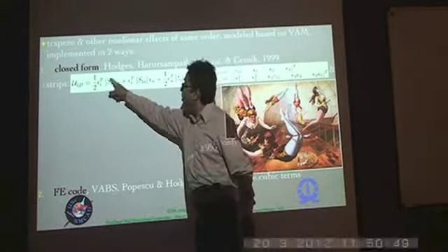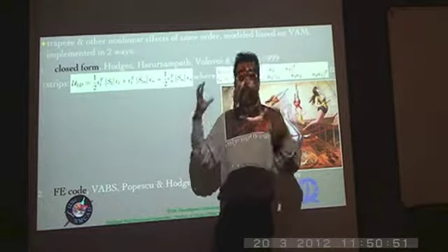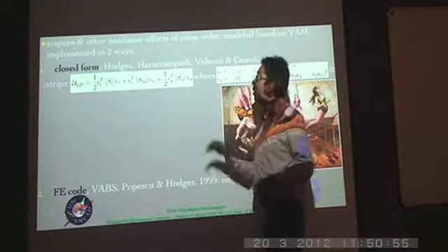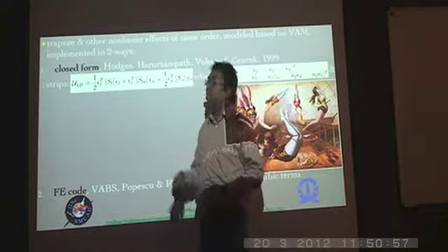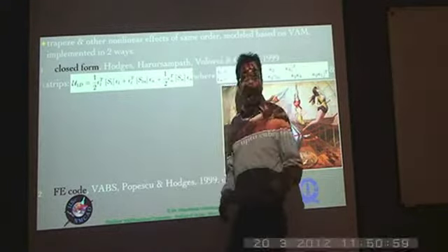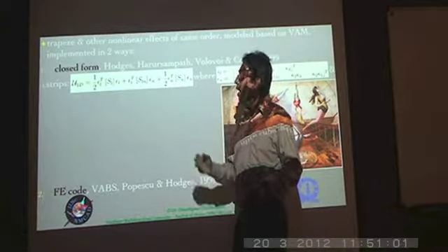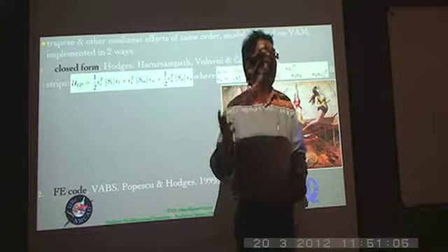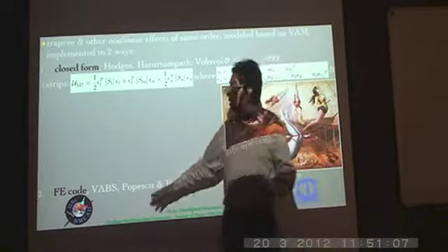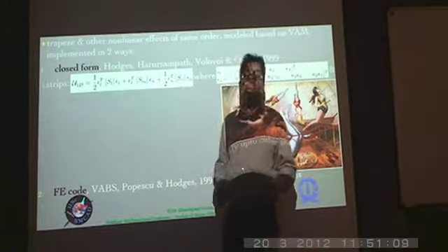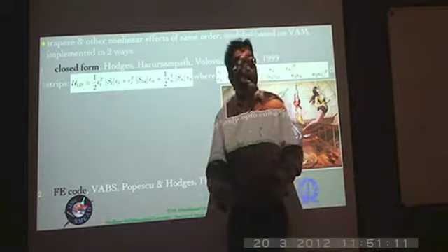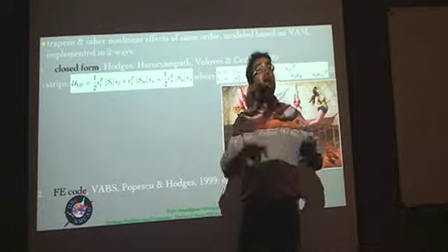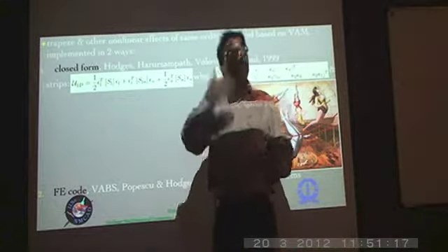And of course the location of each ply with respect to each other. That's the information which goes into that, and because we have been given a particular beam, all these things are known a priori, and therefore SL, SLN and SN are determined as numerical values. The expressions for those are closed form analytical solutions. That's what I mean. Whereas in this other case, those SL, SLN, SN, etc., which are equivalent ways of expressing the same thing, as we shall see in the next slide, will have to be calculated by a finite element analysis of the cross section.